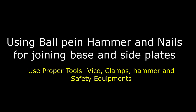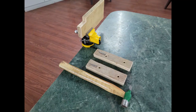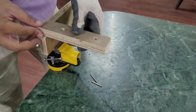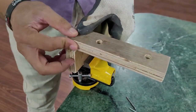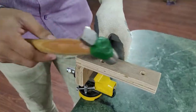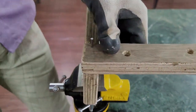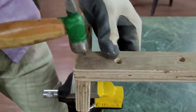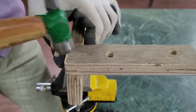Now let's use ball pen hammer and nails for joining the base plate to the other side plates. So clamp the base plate on the vise like this. We are ready with the base plate, and now take one side plate. Make sure that the top hole is aligned on the top, and then use the nail, use the gloves, and carefully nail the plate like this.